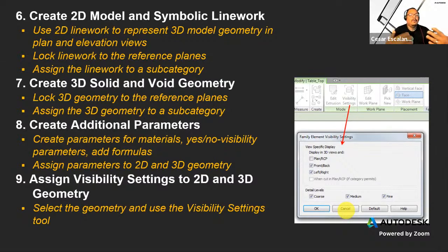Obviously, these doors, I want them to be visible in an elevation view, but maybe I don't want to see them in a floor plan because in floor plan, I just want to see a simple rectangular representation. And so the nested component in the family is automatically disabled to be seen in a floor plan, but it's enabled to be seen in elevation views.